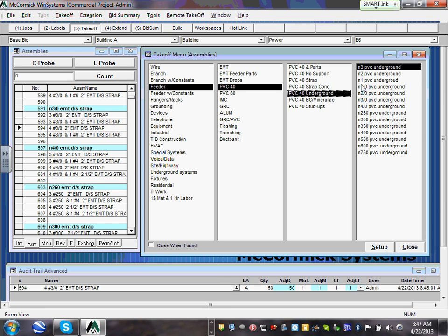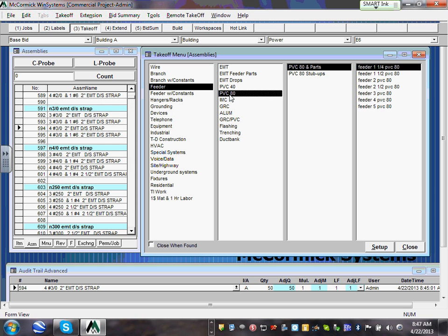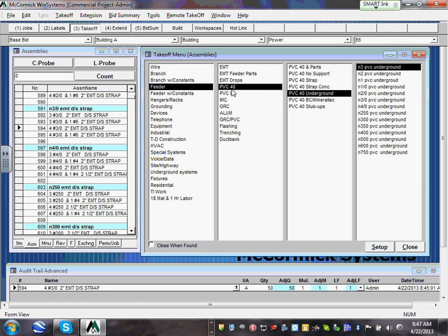So that's where you guys are going to be putzing around, and here's my advice. If you find a conduit with a wire, that's the easiest way. If you can't find a conduit with a wire, what do you need to do? Take it as a conduit and take it as a wire. Okay? So here's a PVC schedule 40. Did we find 80 though, underground? No, we don't have 80. So 40, because 40 is the most common underground. Why do you want to put 80 underground anyway? It's buried underground, so 40 is the most common underground, so that makes a lot of sense to use. Use it for the service underground, but as you exit from the ground, you can just put an 80. Okay, any comments, guys? Any questions about that?